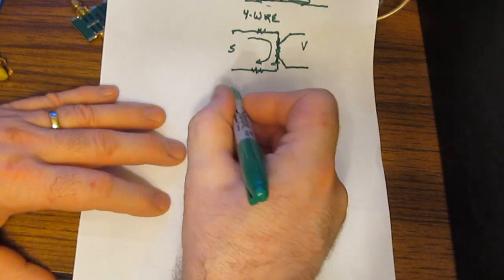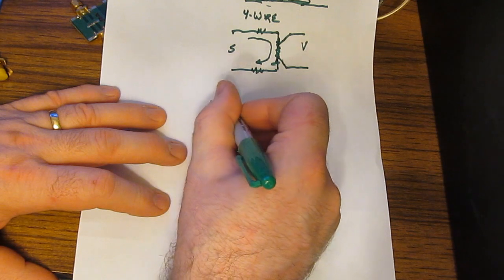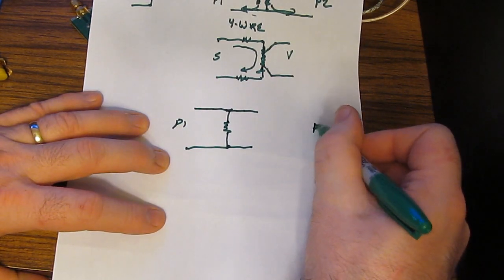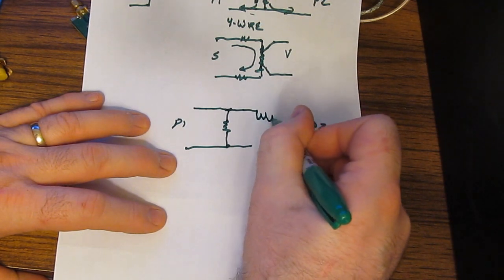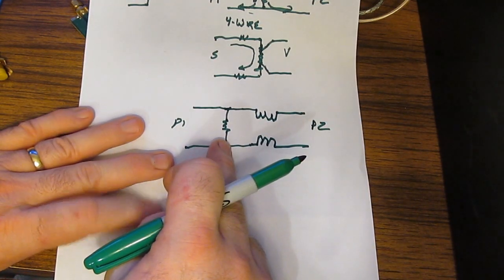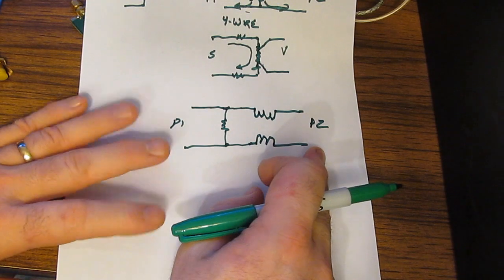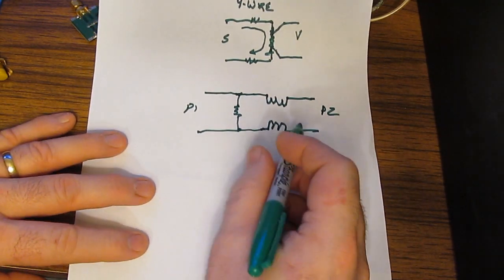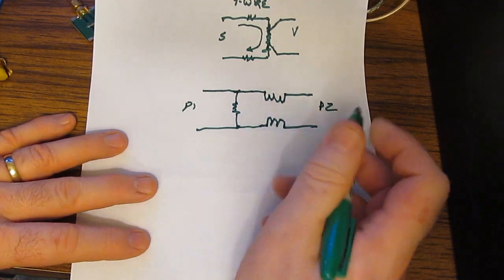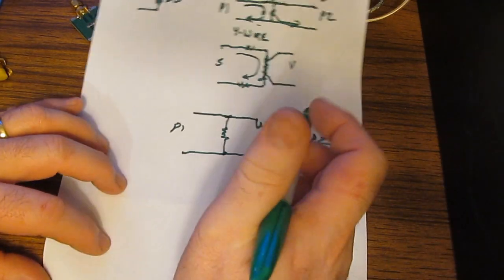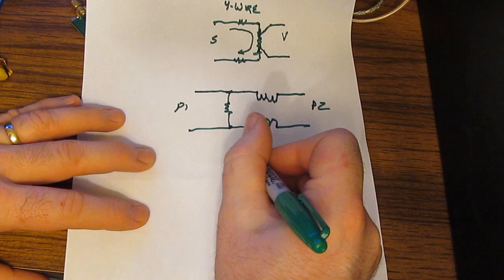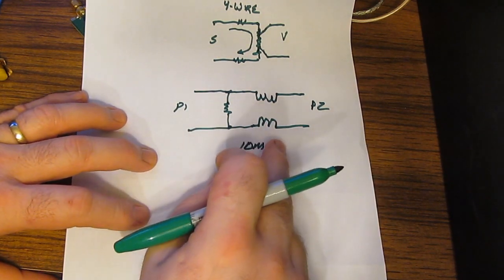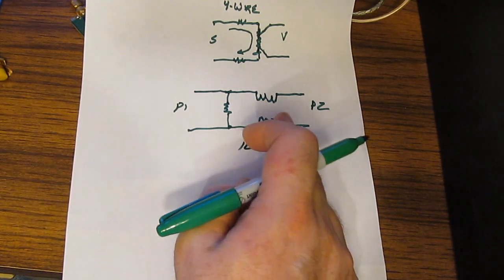One way to do that is to add a common mode transformer. So again, we have port 1, and over here is our port 2. Now we're going to place this transformer between the device that we're testing and port 2. The idea with this transformer is that it has very good common mode attenuation at low frequencies. Typically at higher frequencies, I'm talking like 10 megahertz and up, the coax cable is going to be so lossy that this isn't really going to be an issue.